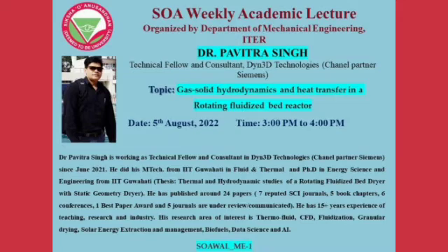So I increased the length from 50 mm to 200 mm in the second case. In the third case I increased the length to 250 mm. In the fourth case I increased the length to 300 mm, and further I tried 350 mm, but the results were very poor because in the direction of length the volume fraction of solid is decreasing or very non-uniform. That's why I preferred the maximum length of this reactor as 300 mm.